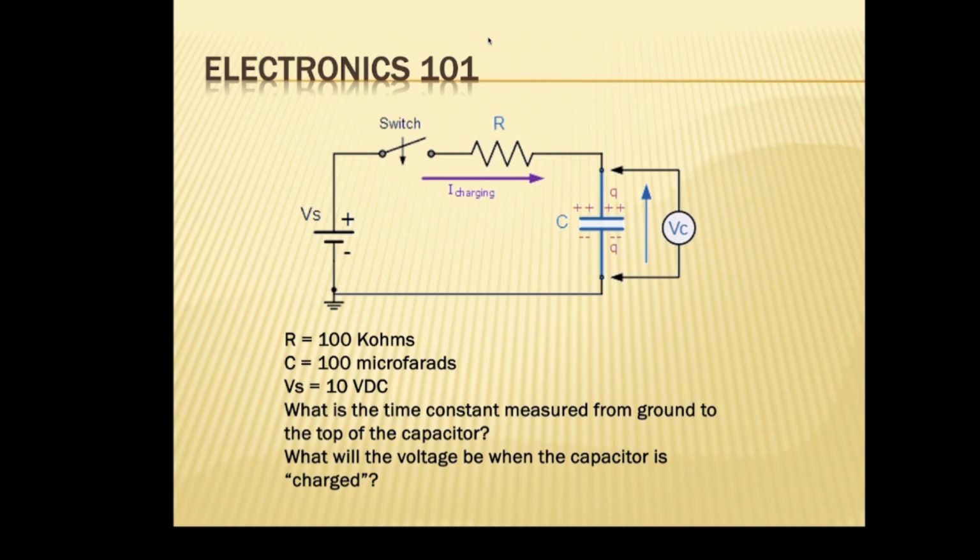In this particular example anyway, we've got a 100,000 ohm resistor in there. We've got a capacitor of 100 microfarads. To make it simple, we use the 10-volt battery. Makes it easy, right? And we put a voltmeter across the capacitor. Switch is open. We read basically nothing unless there was some residual charge there, which is not likely. So we're reading nothing. And then we close the switch.